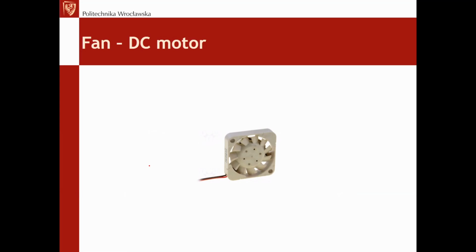So DC motors are mechanically not as sturdy as the AC motors, because internally there are connectors from wires to windings on the rotor, because the windings are rotating here. That's the disadvantage.